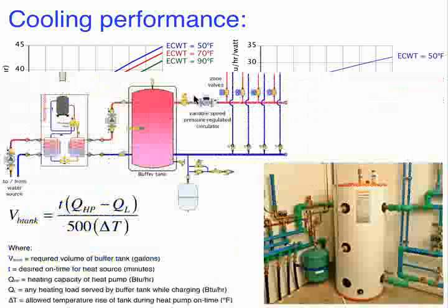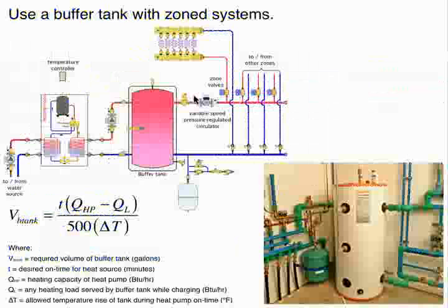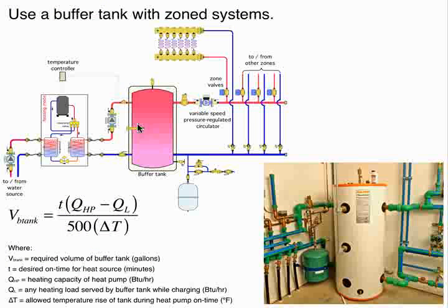It's a similar idea where we have multiple zones. We have an on-off water-to-water heat pump supplying heat. We're putting that buffer tank in between to act as a mediator between the output capacity from the heat pump and what the load could be at some point. And it's also, again, functioning as a hydraulic separating device. This is a geothermal install, again using the Caleffi Thermocon tank. Basically, the heat pumps are over on this side, and then we're distributing over on the right side here.